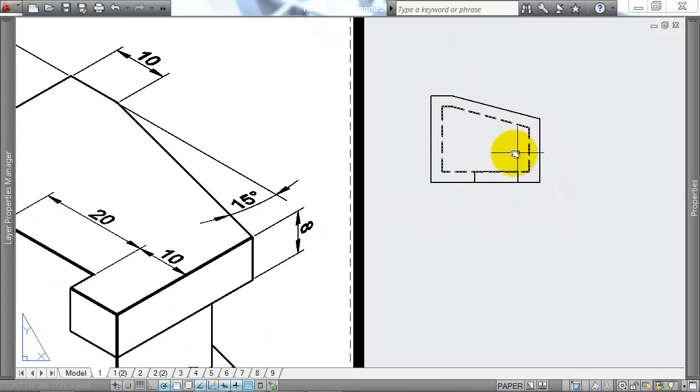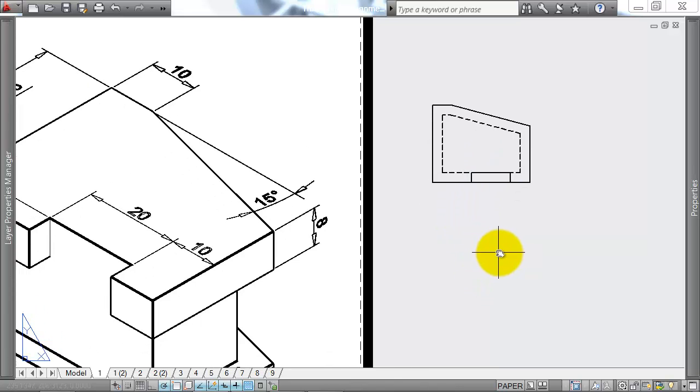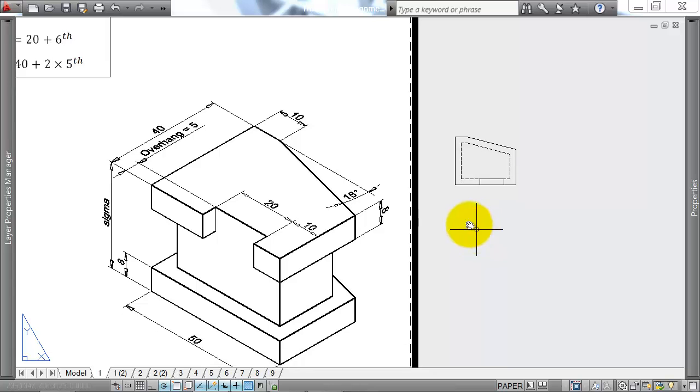So there, that's how we've got this hidden line around there. Might even change the line type scale so it's a bit easier. LTS is for line type scale. Now what other features might we see from this top view?